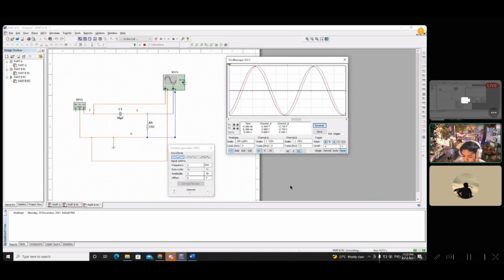So how to find the y and d? First, I will show you how to find the difference between two signals, which is y. I will use this cursor; I will call these cursor 1 and cursor 2. First we need to find the intercept of these two signals to the x axis, so we need to set the y value to 0.